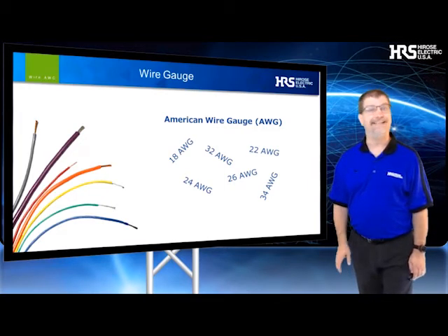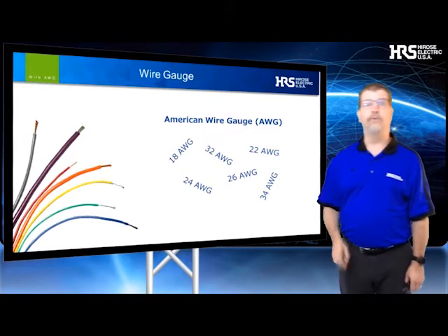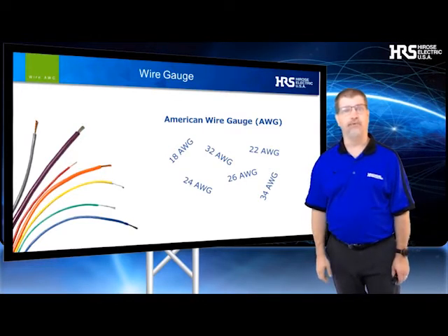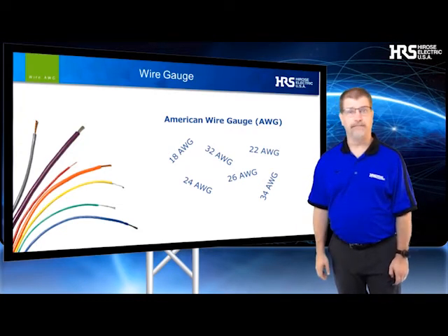So if you are using an 18 gauge wire, but are only using 1 amp worth of power, we will select the smallest connector that has support for the 18 gauge wire. This will save you both space and cost.